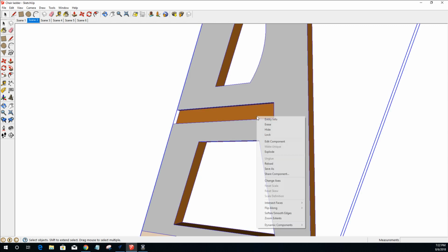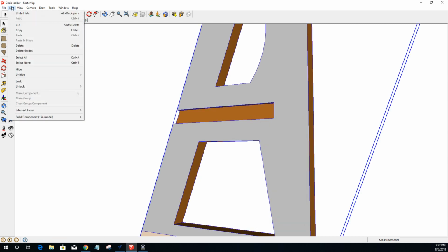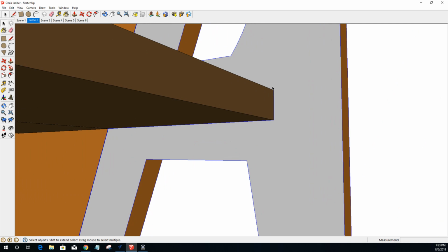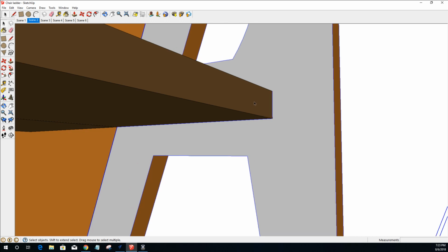But our step that we put in, let's see if I can unhide that last one. We would take our step material and we would round it off as well, round off the edges. Whether we do that with sanding or whatever, we would just take off and create a radius on the top and lower edge so it fits into this area well here. Another thing we could do is some kind of dog bone fillet in the corners in the upper and lower corner, so we could have a square back without having to worry about rounding off the step, either one.